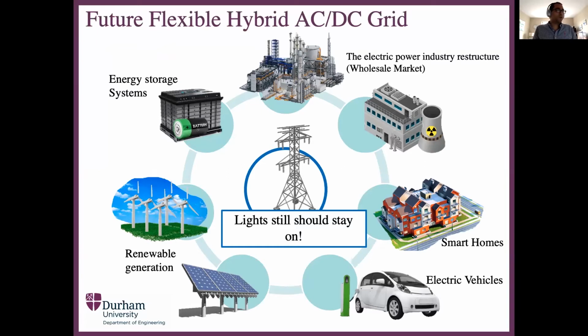Now, we have centralized, larger scale renewable generation, offshore wind, for example, but we do also have domestic wind, rooftop solar. These are normally distributed throughout the network across all voltage levels. So we have the transmission voltage levels, that's high voltage, then we have the distribution, that's medium voltage, and then the consumption, which is low voltage, which is the voltage that we get from our mains in our homes. And we can see renewable generation distributed across the board.